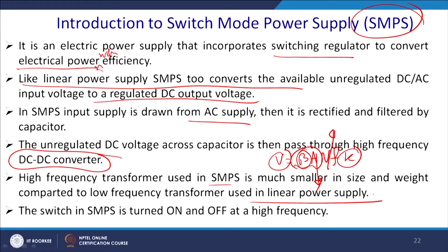Generally most of you have used it for your BTP project, or you will be using it. So, we use the IC regulator 7805 that gives you a regulated 5 volt, and essentially your solution is quite bulky. What you do essentially is you rectify, you use a very bulky transformer of 0 to 12, plus minus 12, actually 220 volt to 12 volt or 9 volt.